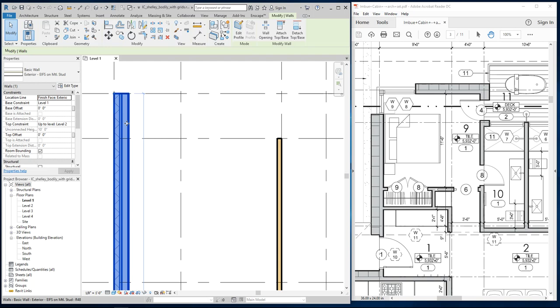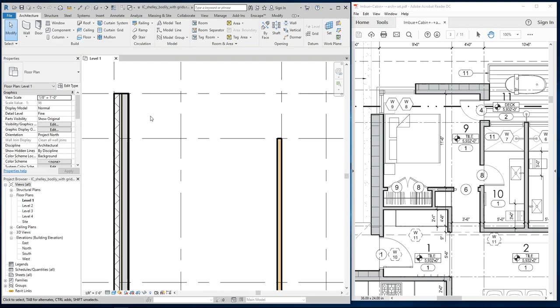The basic setup is already there. You're just changing the parts out, okay? So what I want to do now is create wall type 1 here. This wall type 1 has a CMU block exterior facade, 1-inch air gap, membrane layer, 3/4 inch substrate plywood, 2x6 wood stud wall, and a 1/2-inch gypsum board. That's this wall. All right, so what I'm going to do is find the wall type.